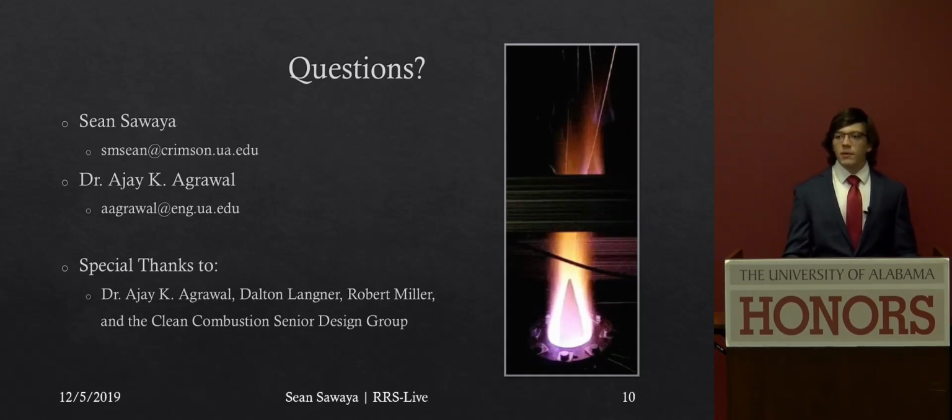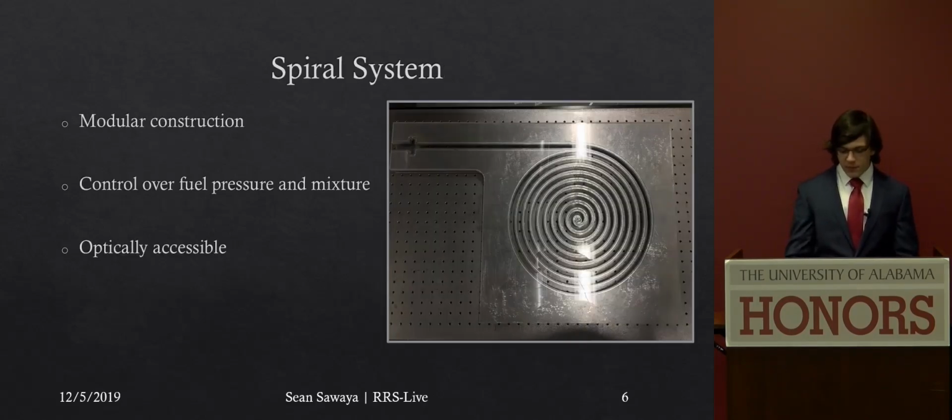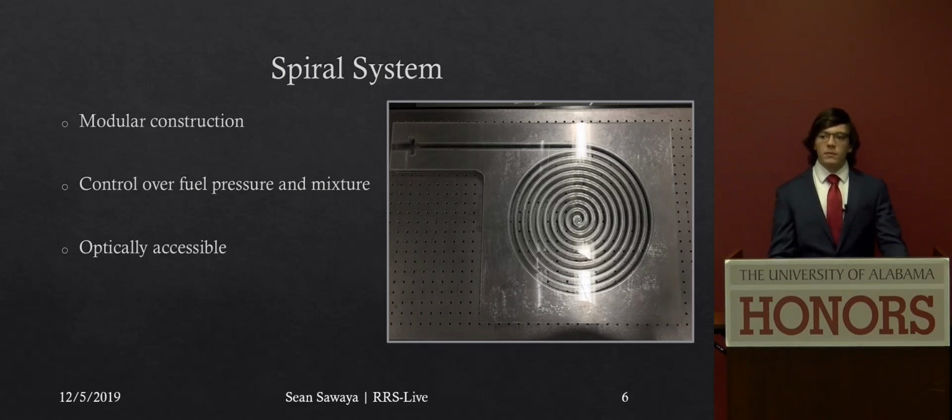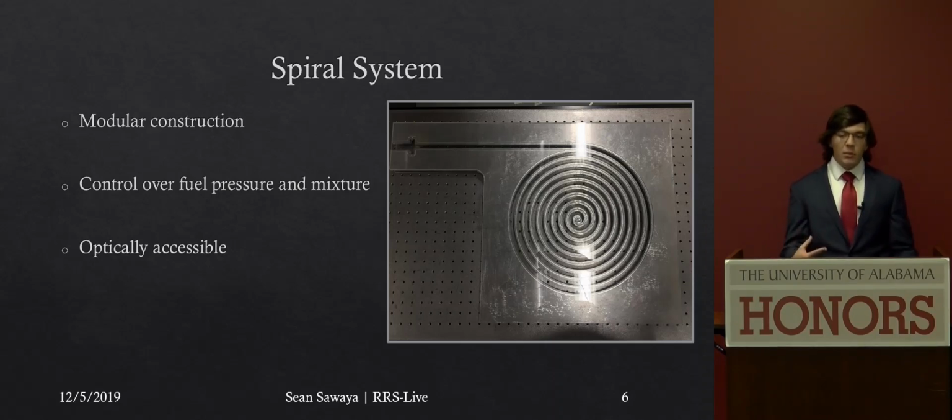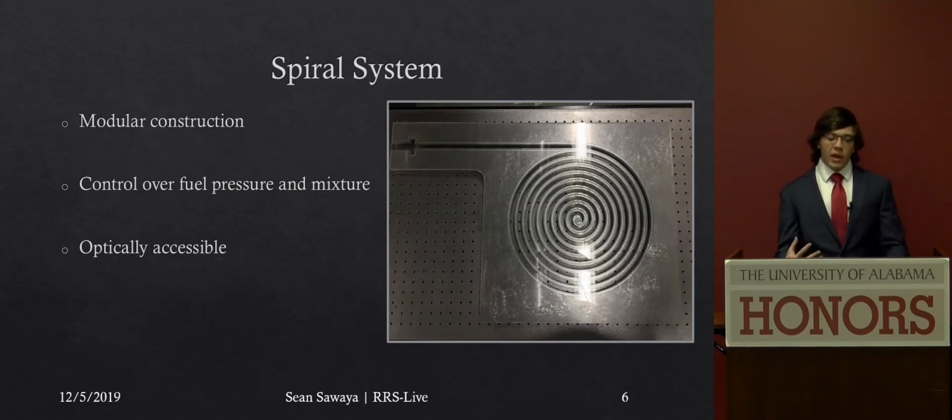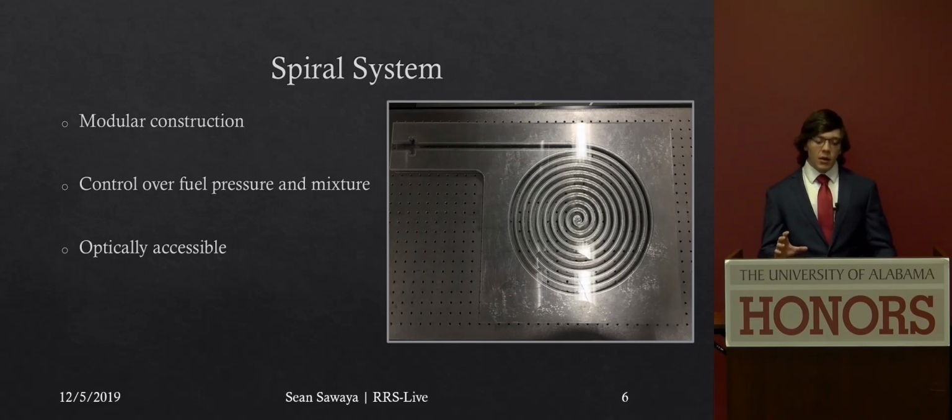John, you mentioned on slide 6 that varying the radius is an important characteristic. Why is radius such an important characteristic? Okay, so the radius is a very important characteristic to us because it will determine the different sizes that we can make these combustors. So we currently know that there is a critical radius at which detonation cannot be sustained. However, we do not know what that critical radius is and how different channel geometries, pressures, and fuel ratios will affect that. And knowing that critical radius will tell us the smallest combustors we can make, which could open up other applications for these kinds of combustors.